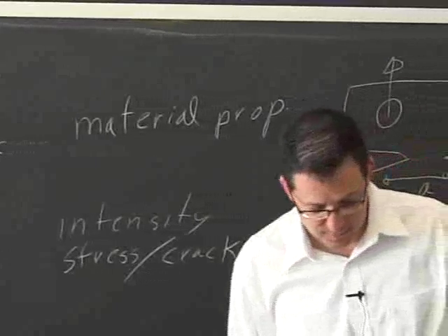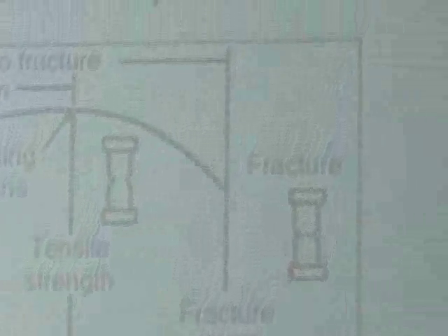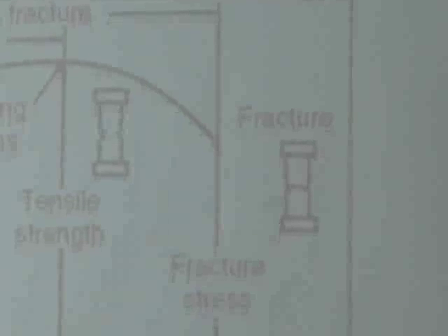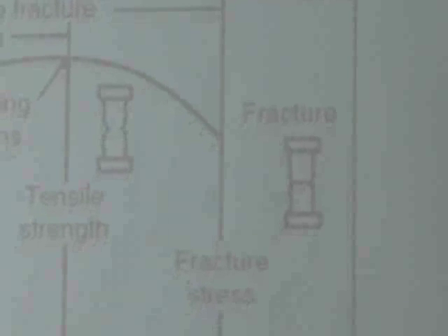The tensile specimen. We talked about it a lot. We talked about the deformation essentially being regular through the whole length of it up to this peak, and that the other half of it corresponds to the formation of the neck, and then we have a local stress that's still higher. So when we make the correction for this curve, we make it locally,